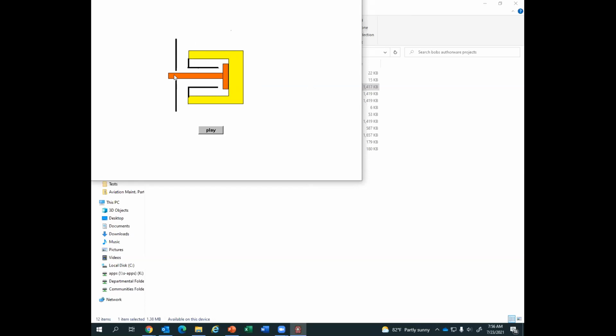Anyways, can you see how far the pin is? Yeah. And see that as the brake pads wear, the pin's going to get shorter and shorter. This is why, if I hit that play, see how far it's sticking out right now? Okay. And then when the pads wear, it's not sticking out as far. So for this type of system, when we're checking the brakes, we measure the distance that the pin is coming out. And if it's too short, we know it's time to replace the pads. Okay. All right. Cool.